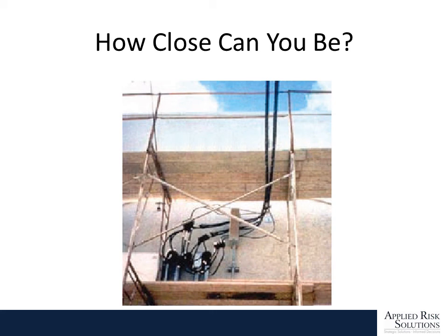Keep in mind, the scaffolding is touching the ground. It's made from metal. So if you were to be touching the scaffolding and touch those wires, or even get close to those wires, you could become part of the circuit.